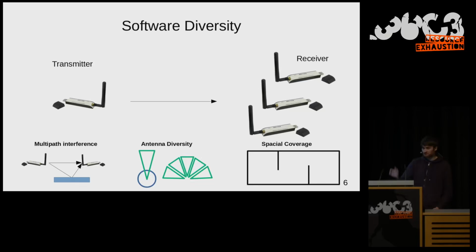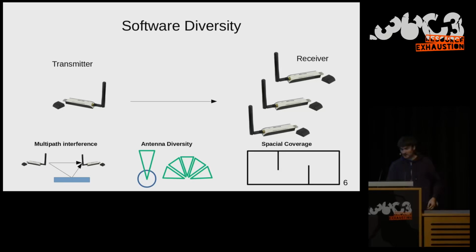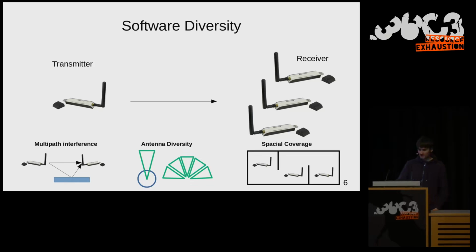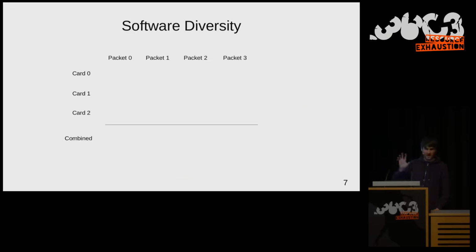So there are situations like this top-down view scenario where you have occlusions which the transmitted signals cannot pass over. And in that case, you can simply place several receivers at different locations, and the software will automatically fuse the signals from these receivers so that you get, in the end, only one logical data stream out of that, which does all the handover stuff and everything automatically from one stick to another. Let me quickly explain to you how this works.